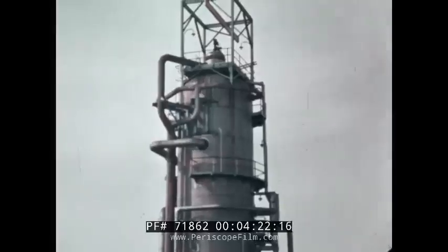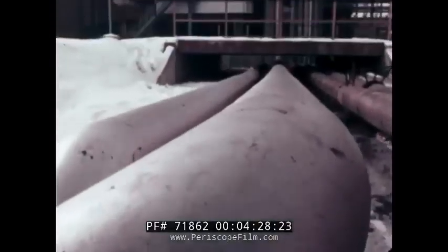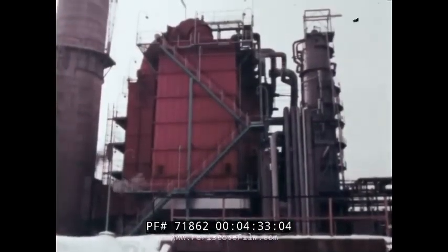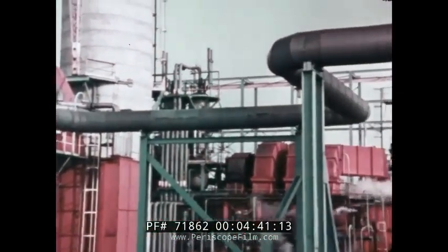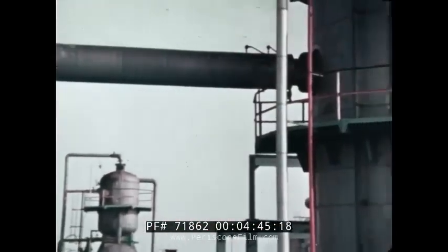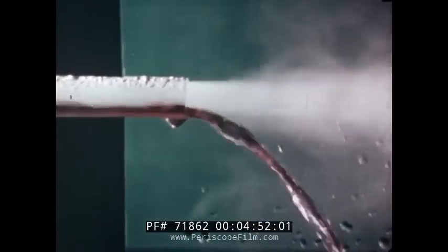First, crude distillation. Through these pipes, crude oil is pumped continuously from storage tanks to a furnace where it's heated. But it's only made hot enough to vaporize some of it. When it reaches the column, the crude oil is a mixture of vapors and liquids. Once inside, vapors and liquids part company.